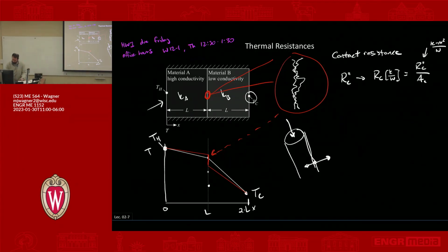Over time, you're going to start getting accumulation of debris or precipitants on the internal surface, where the air is flowing through here. So you might get this kind of thin layer that builds up on the inside of a tube. Any real industrial process is going to have this because you have impurities in the substance. As that builds up, it introduces an additional thermal resistance. And that can be a significant thing. It can actually change the temperatures in the system. So this is called fouling resistance.